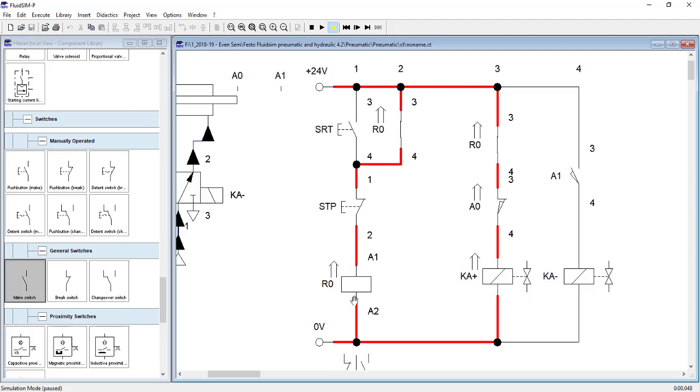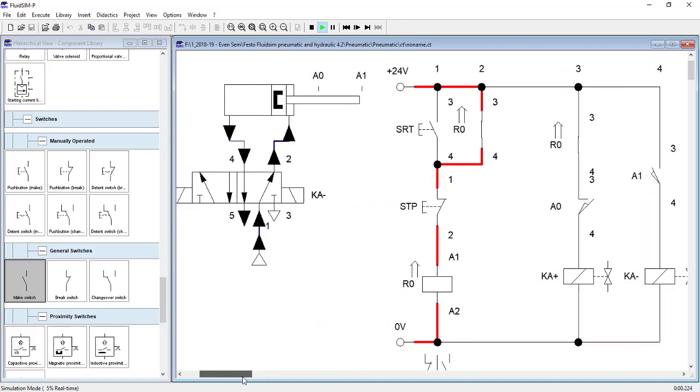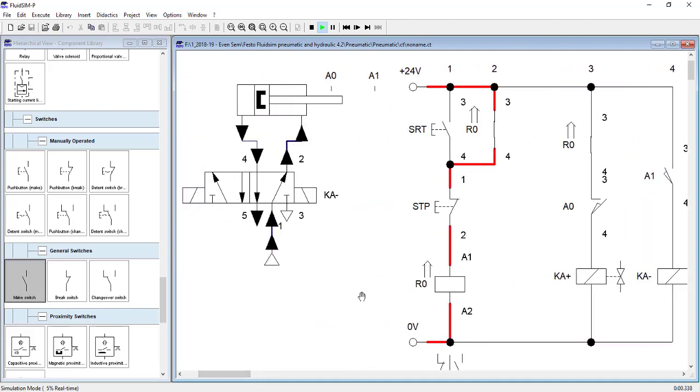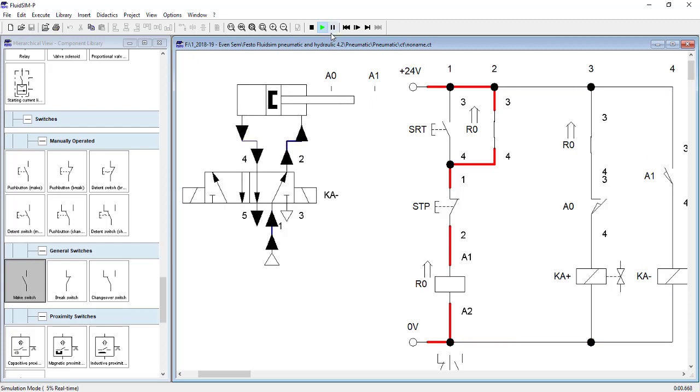So what is relay 0 doing? The relay 0 is keeping itself on. It is using a NO of itself to keep itself on. Right? So now this system will work completely automatically till I push the stop button. It will keep on working, right? Now what will happen when I push the stop button? I will pause it again and bring it to the last step.